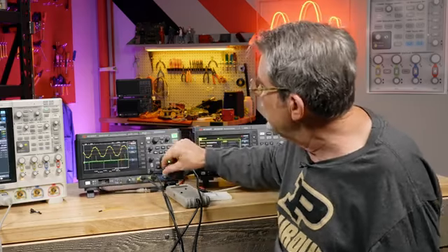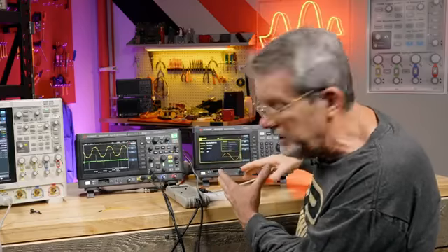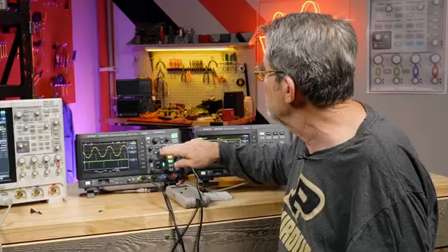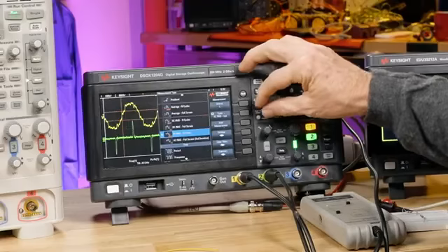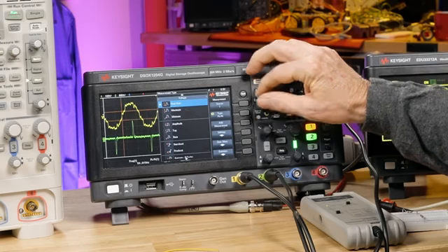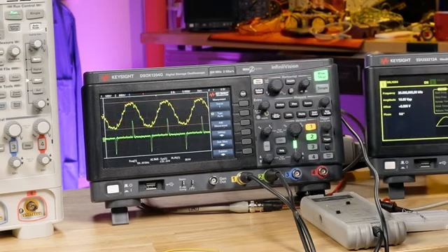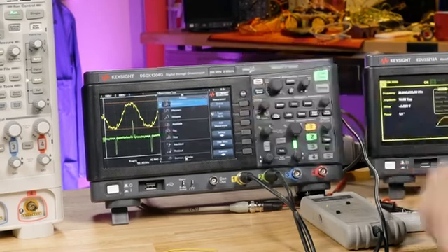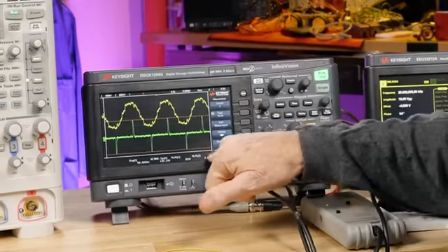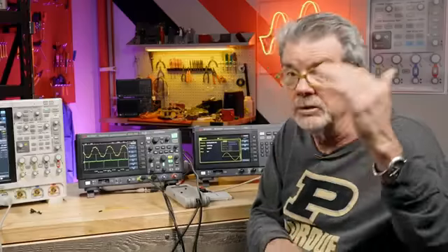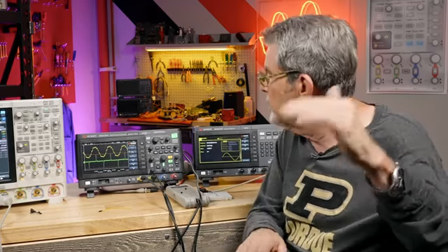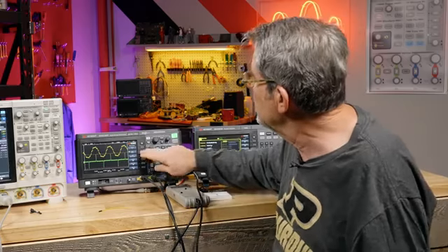Let's make some measurements on that. And by the way, I'm not driving anything with this generator, and so it's not pulling a lot of current. Let's do a peak-to-peak measurement on this current. So peak-to-peak is, oh, I selected peak-to-peak voltage again. Let's do peak-to-peak current. It's almost 4 amps peak-to-peak, so it's approximately plus 2 amps peak, minus 2 amps peak. Let's do the RMS.